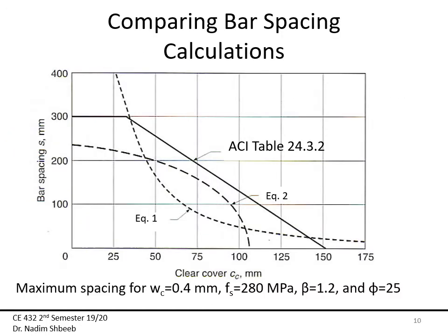Now, why this equation? Well, if we look at the equations developed by Gergely and Lutz, which were equations 1 and 2, you can see that if we draw the bar spacing S versus the clear cover CC, they meet only at 2 points here and here, and they're widely different everywhere else. So as a compromise, I'm going to come up with a new equation that will take those two in perspective, and hence this is my table